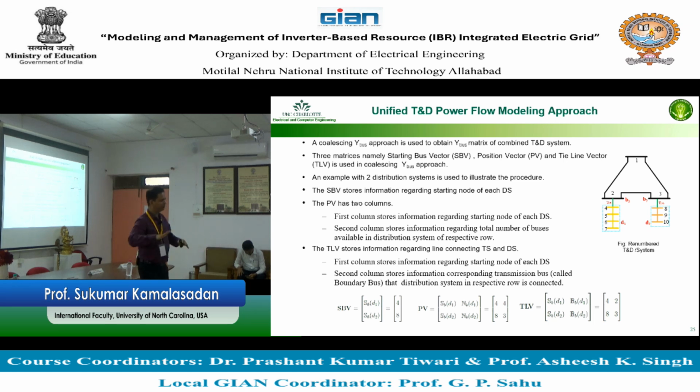That you will do with a distribution power flow. If the distribution voltages are not good on the distribution network, you will put in LTC and you will put in regulators. Remember that slope which we talked about, right? So you maintain that slope proper.